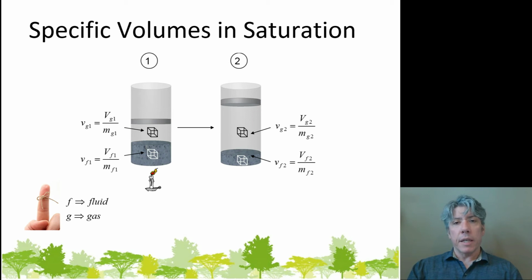What I would find is that the saturated vapor has the exact same amount of mass in that volume. As long as I take the same amount of volume, I'll find the exact same amount of mass. In other words, the properties of the vapor are the same regardless of how much there is of it. In the same way, the specific volume of the liquid is the same in both states.